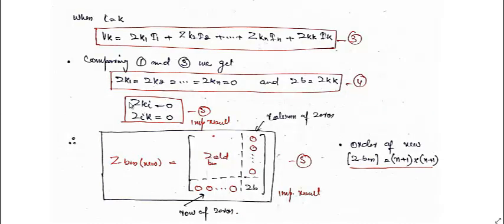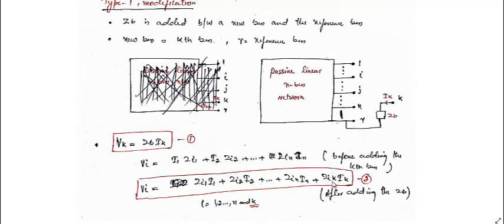That means when I represent it in general form, Zki is equal to 0. Since we are assuming the system to be symmetric, Zik will also be equal to 0. That's why I have taken that this Zik will be equal to 0 for any i from 1 to N, excluding k now. Because it will give us actually the row of the Z bus.